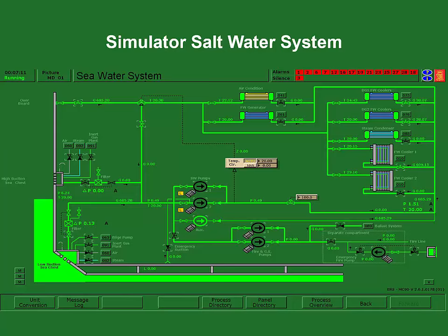You still have that, but now the systems are quite small, so that reduces the amount of maintenance. And I want to think too, the saltwater systems are more expensive because you are using an electrolyte, the salt water, and also that you end up having to put in systems to kill the marine organisms coming in. Also too, the lines and the valves and the pumps have to be made out of a corrosion resistant material, or in the case of a lot of modern ships now, the inside of the piping is all rubber coated. But this all adds to the cost as well as the maintenance.